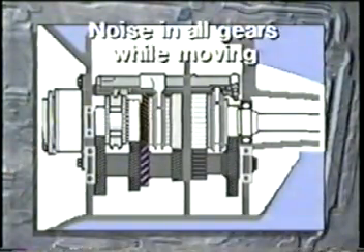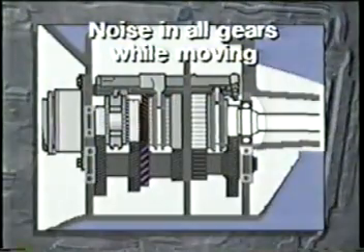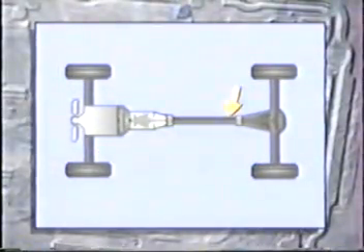If you have a noise that occurs only while driving, and it occurs in all gears, it may be the output shaft bearing. Be sure to eliminate wheel bearing, axle, and driveline as possible causes before disassembling the transmission.